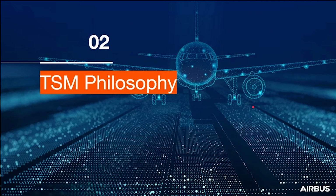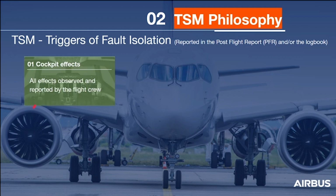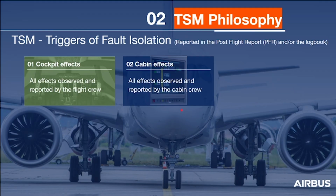Now let's move to the TSM philosophy. So what are the triggers of the troubleshooting manual? In fact, we have five. So we have cockpit effects, all effects observed and reported by the flight crew, like for example, an ECAM warning. Cabin effects, all effects observed and reported by the cabin crew. As an example, a failure under the FAP, flight attendant panel.